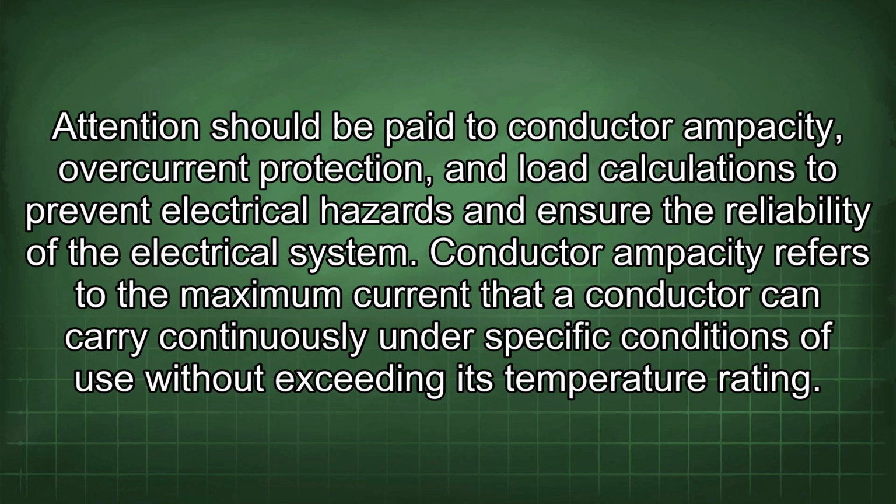Attention should be paid to conductor ampacity, overcurrent protection, and load calculations to prevent electrical hazards and ensure the reliability of the electrical system. Conductor ampacity refers to the maximum current that a conductor can carry continuously under specific conditions of use without exceeding its temperature rating.